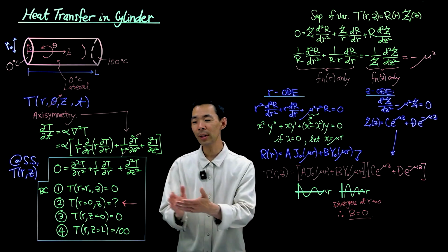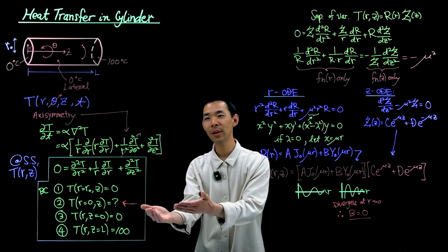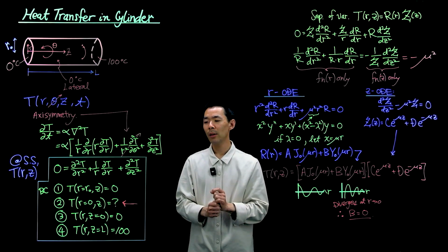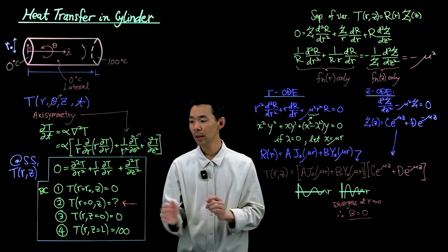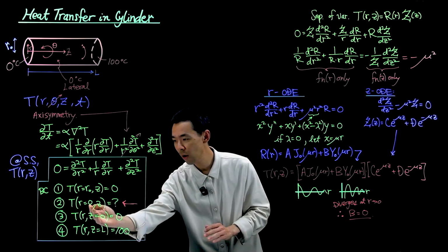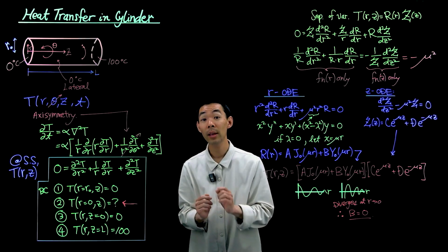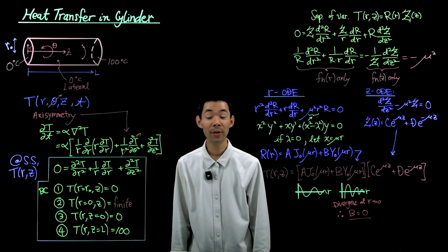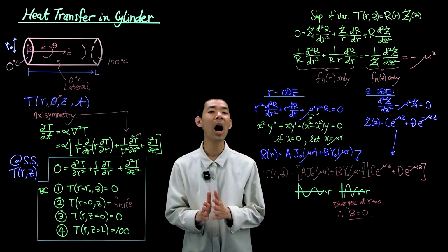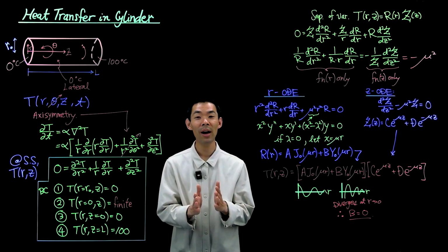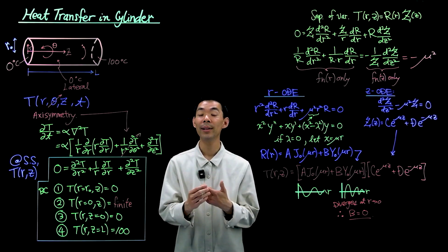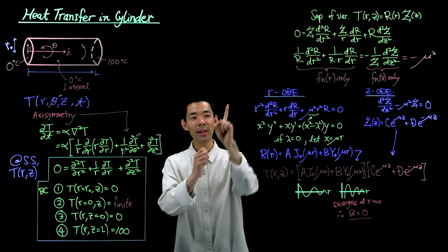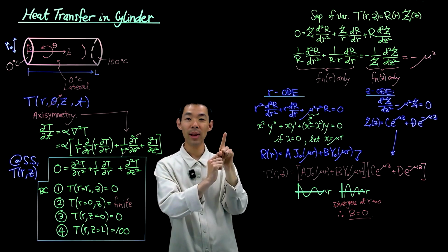So now, returning to this mystery boundary condition that we've kind of left untouched for now, we can make that more precise. The temperature profile, as r goes to 0, must be a finite value. This boundary condition is a very common one that we apply for cylindrical and spherical coordinate systems, with the radial direction that emanates from some origin outward.